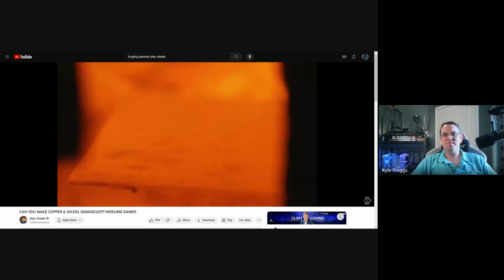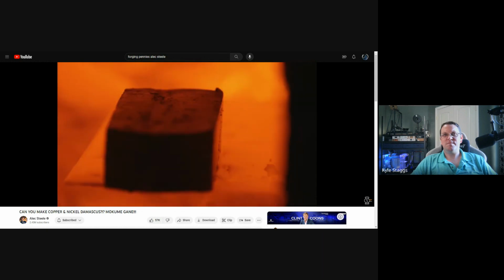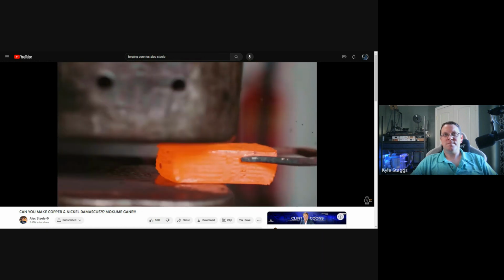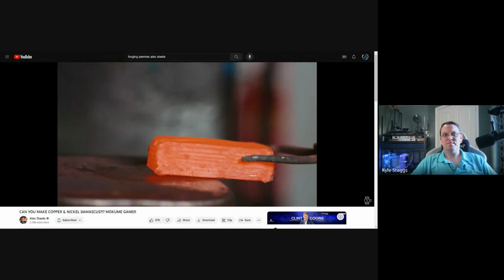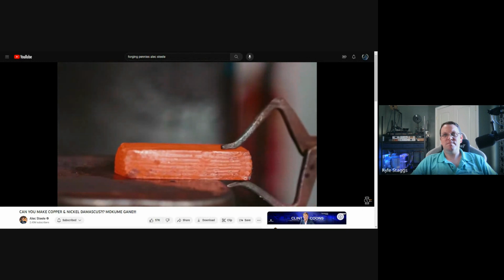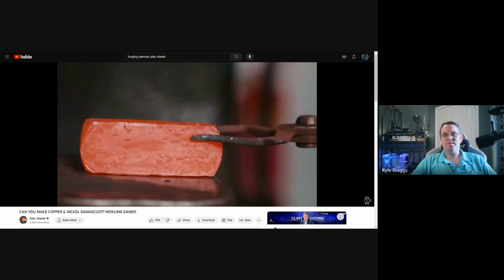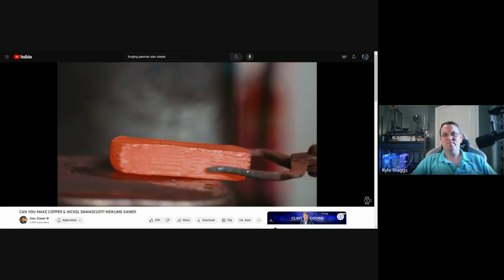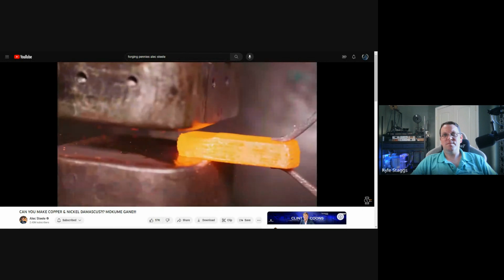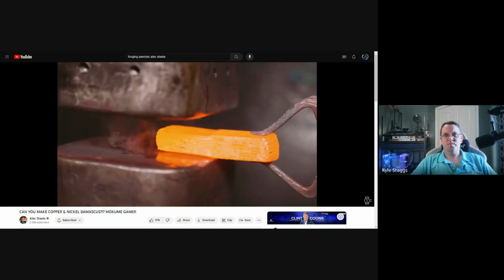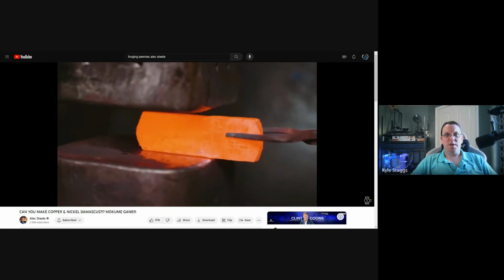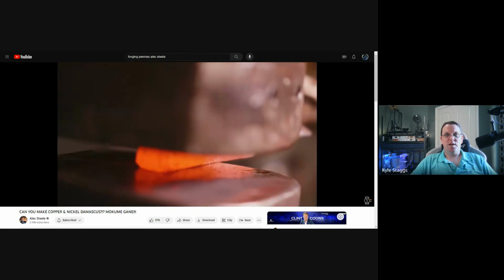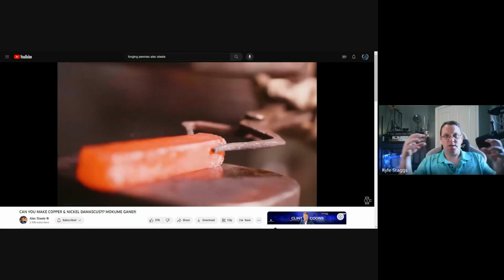So I put a block of steel on the floor. Oh, and I missed it. I will heat it up on there, see if that keeps it a little cleaner. Right, let's forge it out some more. Uh-oh, that's not good. Maybe I'm being a little too aggressive. The grains are being elongated, all in one direction, being stretched lengthwise.